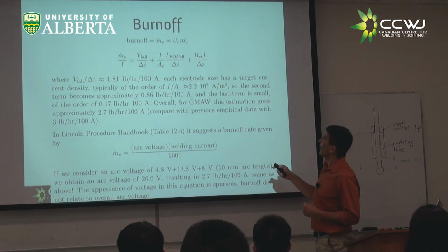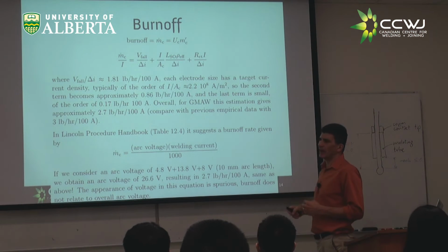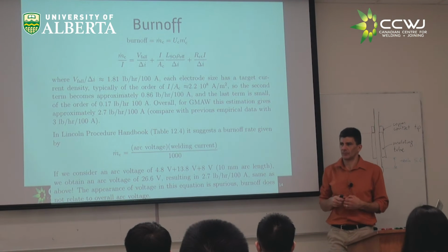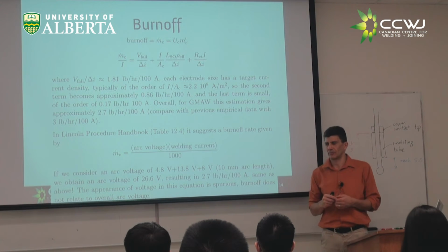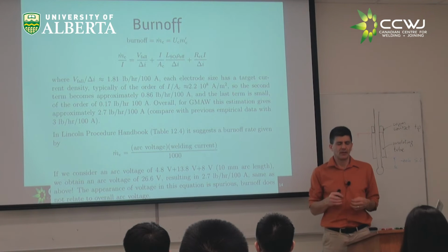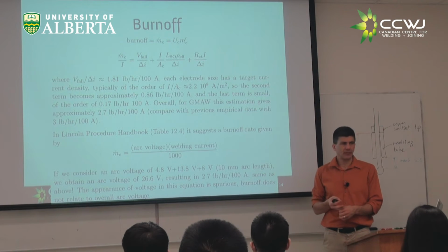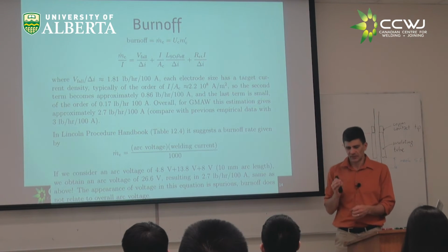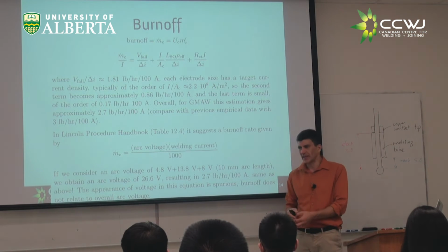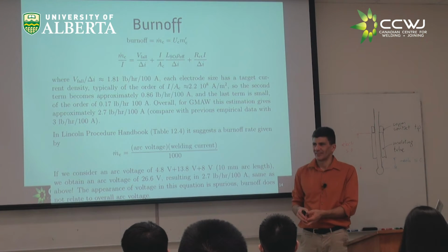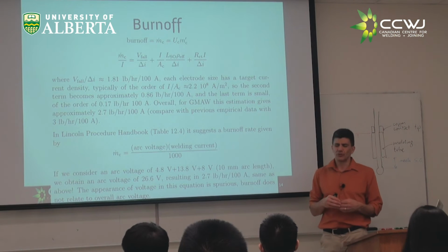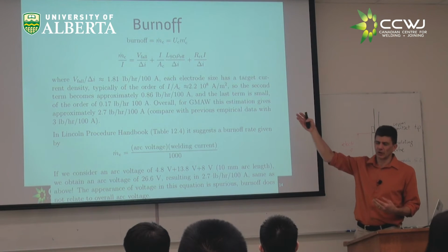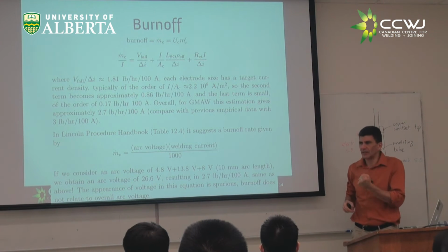So this is 220 amps per square millimeter, give or take. When you want to put too many amps in a thin wire, people would say, no. Let's put those many amps on a thicker wire, right? So in the end, you don't go with crazy high currents in crazy thin electrodes.